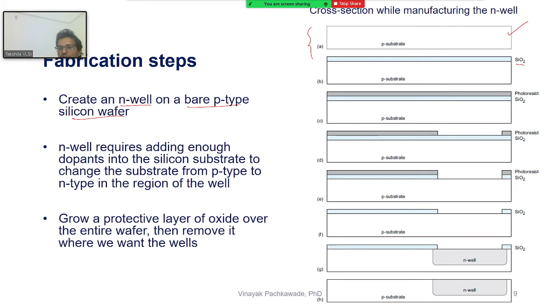First you grow a thick oxide, called silicon dioxide, on top of the material. On that, again, as I said, you deposit and grow a photoresist. That's again the polymer, an organic polymer material. Why photoresist? Because that's the step of patterning your design.